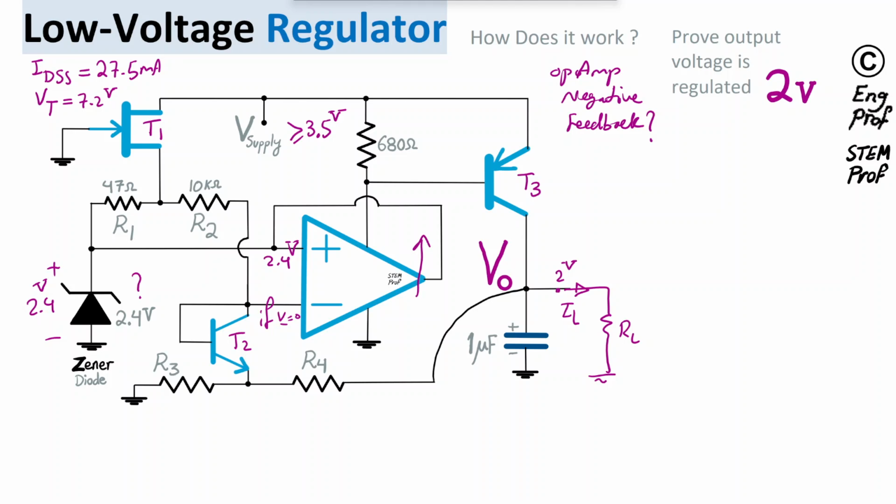As a result of trying to boost up the output voltage, there is an increasing current going through the 680 ohm resistor to the positive supply of the OpAmp, to drive the output transistor inside the OpAmp, so that more current is provided at the output to drive up the output voltage.